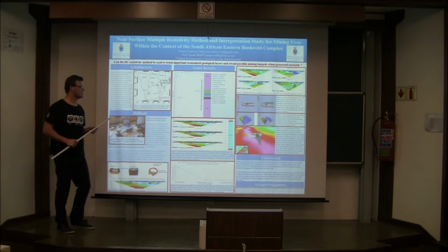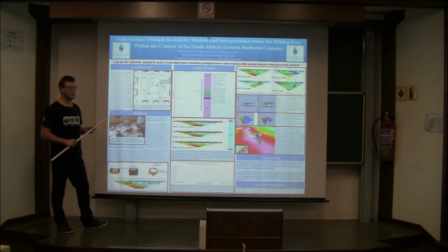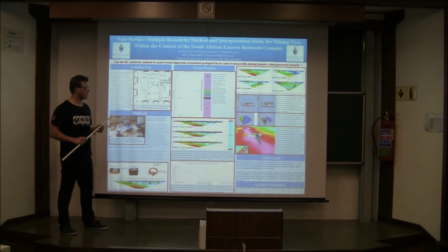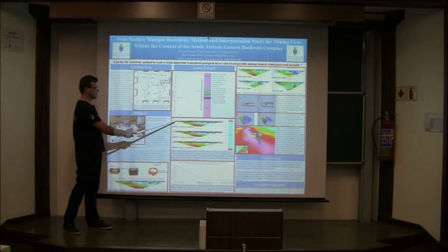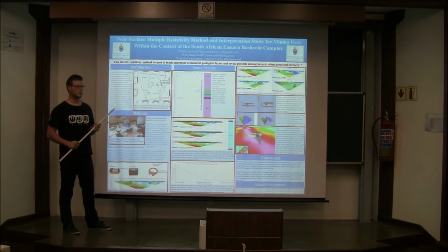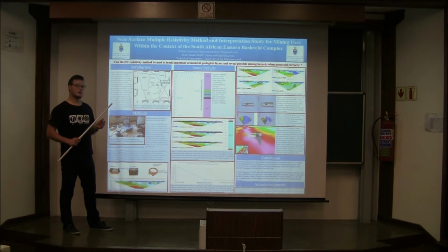The second method I use is 2D resistivity profiling, where I constructed the resistivity profiles near exploration walls, once again using the automatic resistivity unit, also known as ARES. I then use three different processing methods to test their feasibility within exploration. The first two profiles you see here are field processed and bad data point removed processed. Now, these are the most general forms of the resistivity profiles we find in exploration. The third profile, however, has been carefully processed and analyzed in accordance with the surrounding geological environment.